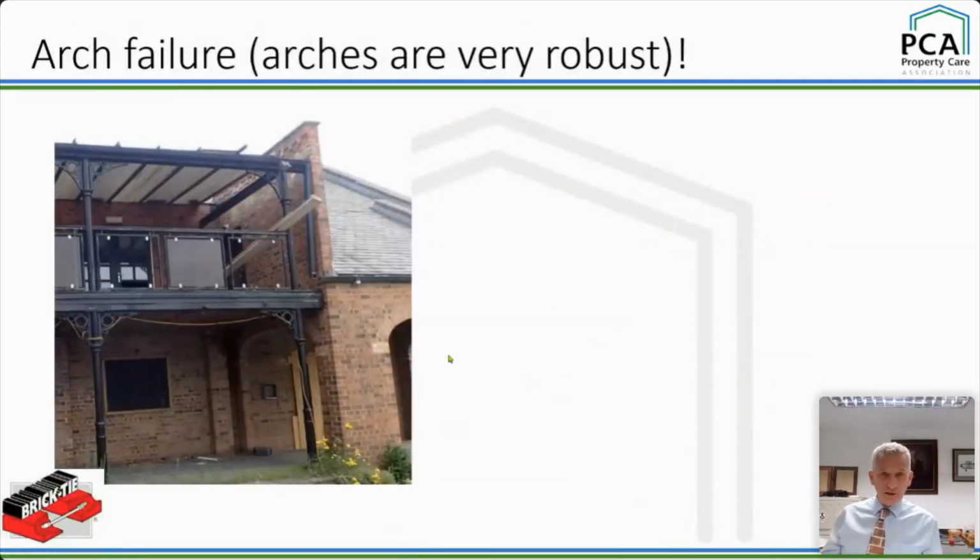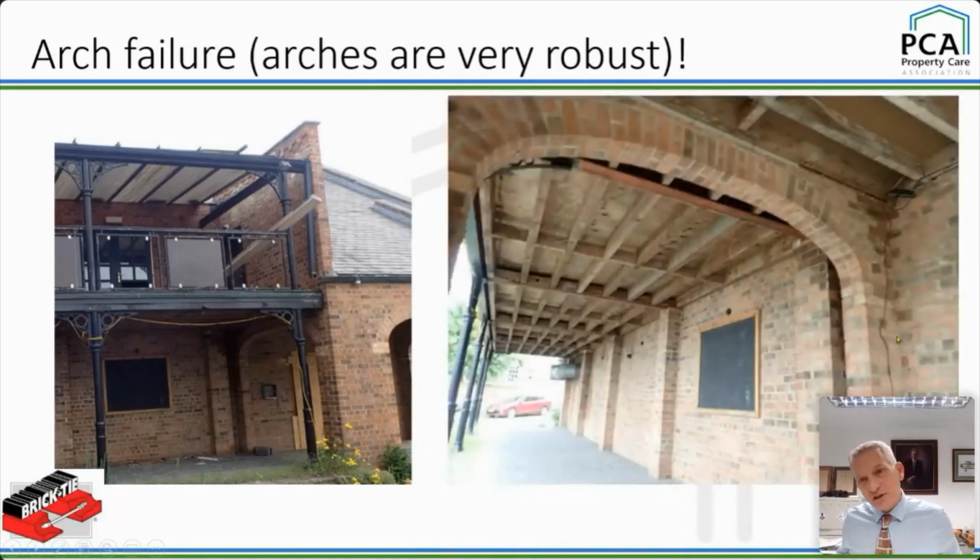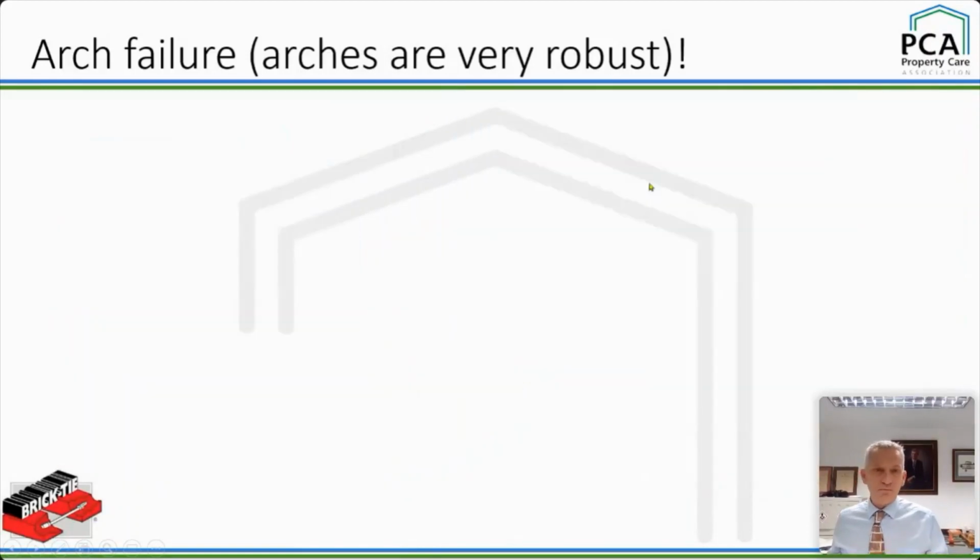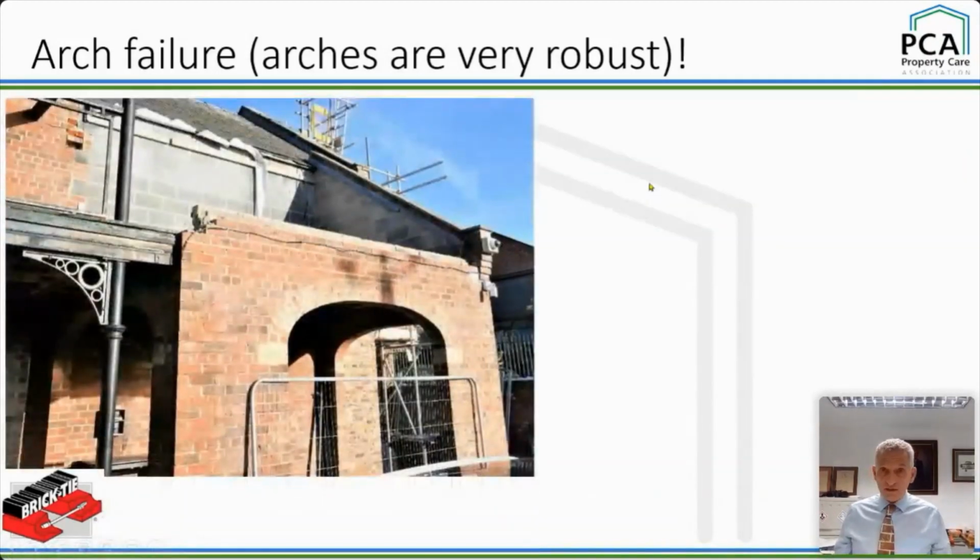Right, so arch failures. I just want to underline the abutment thing. Here is a job I looked at a few weeks ago. It's got a very shallow arch, and look there, there's brickwork above it. And that's the very shallow arch. There's 3 of them, not a crack in it. I went back last week. Amazing that we're going to do this talk, really. And they've taken the masonry off. They've taken the load off there and the load off there.